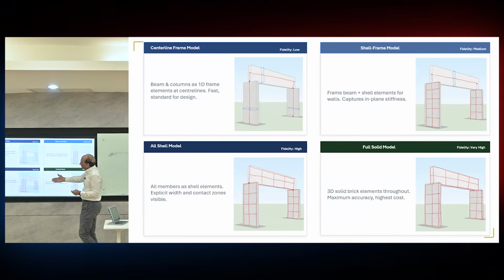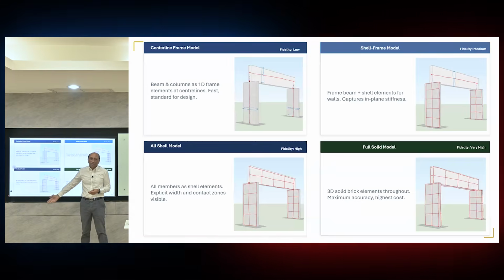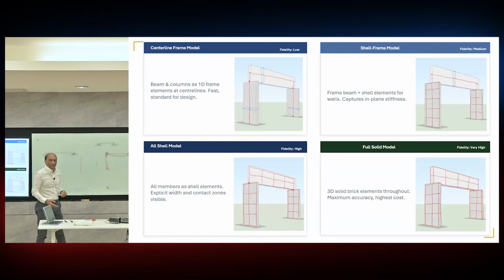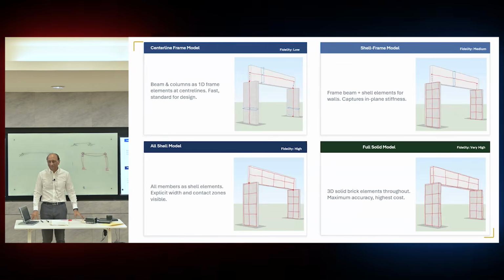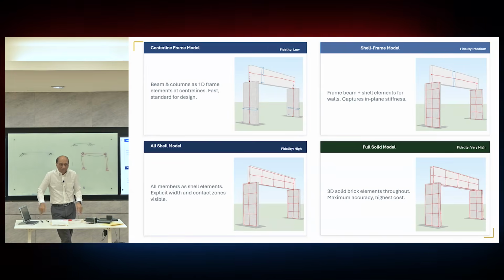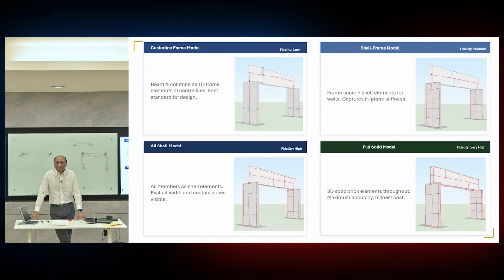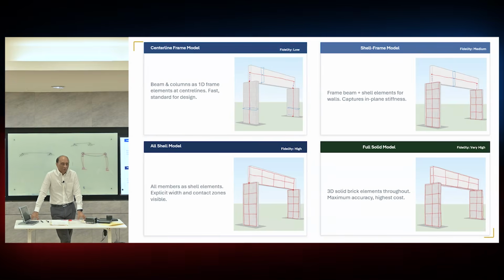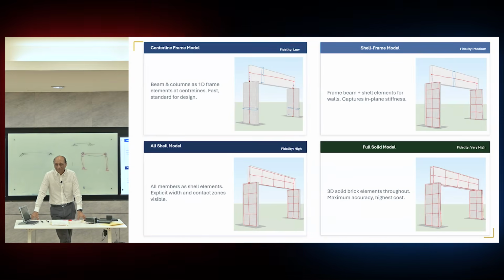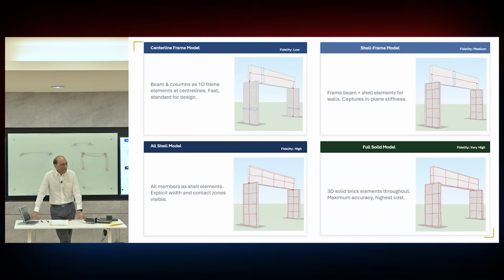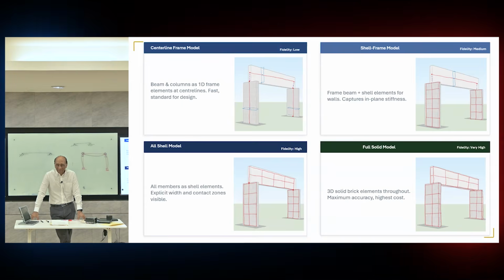The other problem is that this is a brick. How do you calculate the shell properties of a brick masonry wall? This is not concrete. Each brick is individual. Each brick can separate from each other. So you are trying to represent it all by a single shell element. What about all the bricks inside? What about their joints? You didn't solve that problem also.